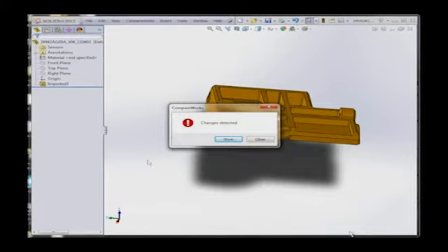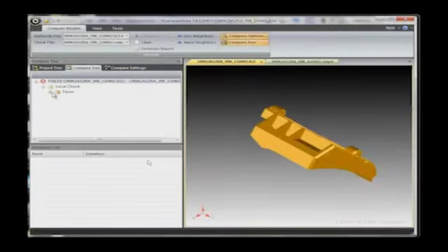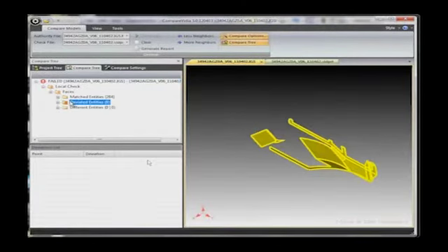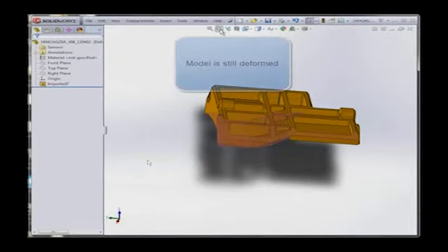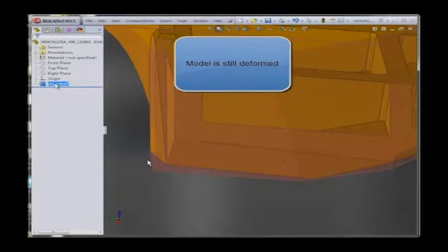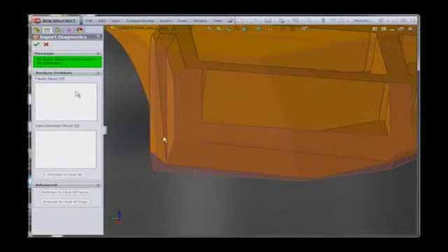But there comes a point where you still need to know if it's right. So here you can run Compareworks from our menu and say, validate models. When you hit this command, we ask you to give us the external data model that was used to import into SolidWorks so we can do, again, this external audit. In this case, it's the IGES file. We bring it into our geometry kernel, and we compare it against this representation. Change detected. Okay, we still have some issues here. Let's take a look at those. Again, still have those 8 deviated entities. They haven't been changed. The SolidWorks model's still deformed.